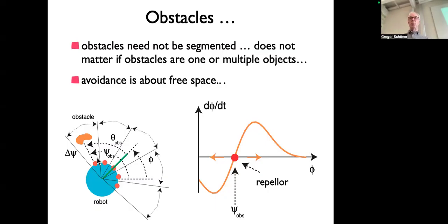In the more ideal case, it will be a time of flight sensor like a LiDAR that gives you precise distance information. Our sensors actually are just some function of the distance. And you would have a discrete number of these mounted on your vehicle, fixed, screwed to the vehicle, so they don't vary where they look.